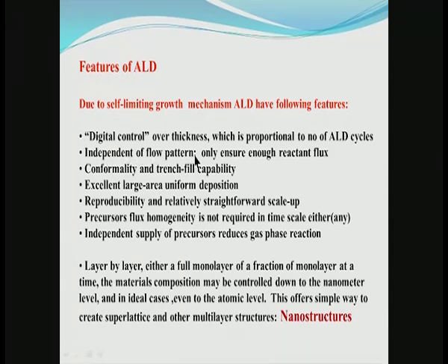One of the big problems with CVD, or at least an important issue in CVD, is the design of the CVD reactor, so that the flow is proper in order to obtain layers of uniform thickness. But in ALD, since we are pulsing the precursor, there is no flow, and therefore, all we need to do is to ensure enough of reactant supply through pulsing.